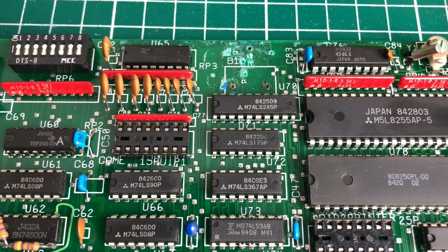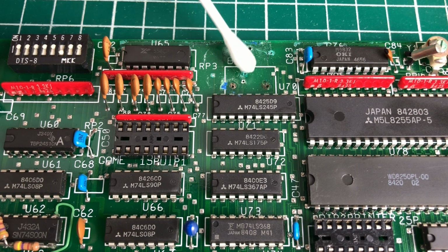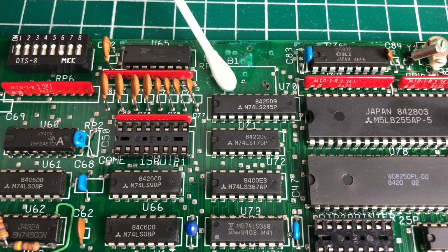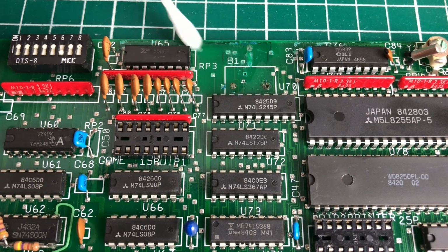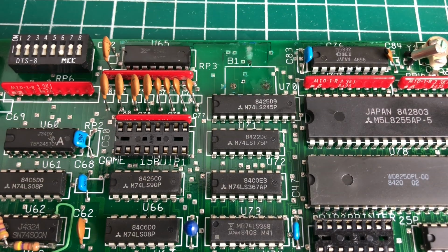So to remove this corrosion, I'm going to be using some white vinegar using this Q-tip. I'm just going to put it on the affected area, and you will immediately see that it starts doing its thing, and it will clean up the PCB quite nicely. Obviously, if there are traces that were damaged because of the battery leakage, we will need to fix those.